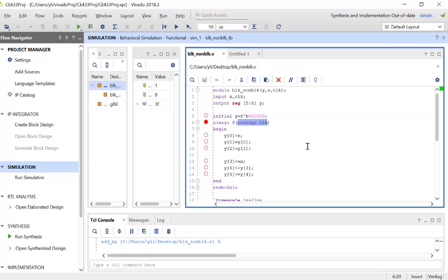That's why all the EDA tools are super powerful. For people who have taken digital electronics doing VLSI design, when you are redesigning the whole circuit, just making it from rising edge to falling edge takes hours and hours, sometimes days, to modify the circuit. But here, it only takes a second. If you want to change it from rising edge triggered D flip-flop to falling edge triggered, just delete POS and change it to NEG. So it becomes negative edge triggered. It's going to change the whole design of the circuit.